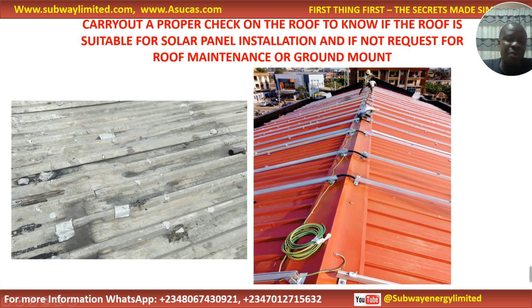Will you be able to mount on the old roof? You cannot do work on this. Everywhere will be dripping water. When you finish, the people will not be able to stay inside the roof again. So it's important for you to bring to the notice of the client that this roof is not good for solar panel installation. So carry out a proper check on the roof to know if the roof is suitable for solar panel installation, and if not, request for roof maintenance or ground mount.